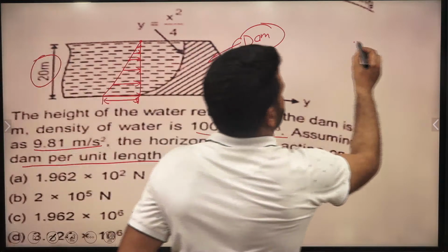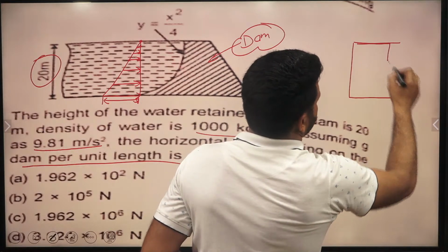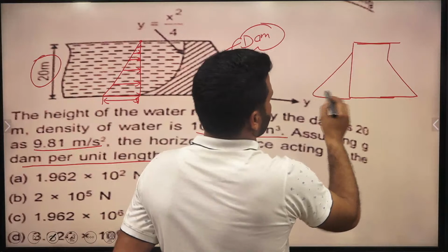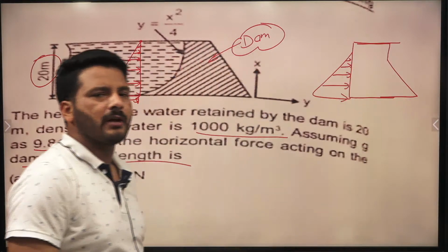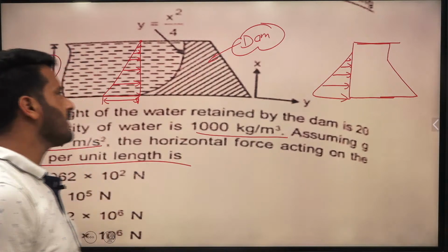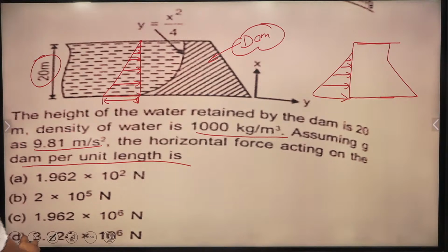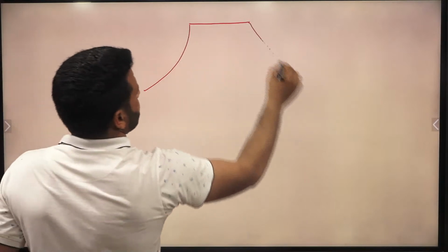If it is like this one, then okay, that is in case of the gravity dam, then it was okay. But right now, the water pressure distribution diagram is okay, but how to calculate this horizontal pressure force is a separate thing. We have to use the curved surfaces concept here. So I am doing it here. This dam is given to us like this one,